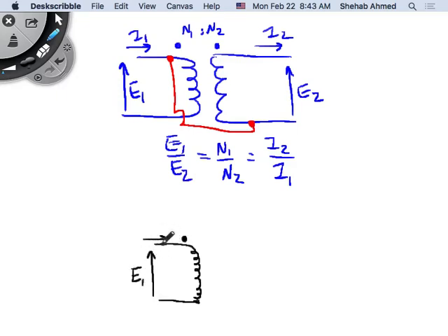The current coming in is still I1, right? But now I took this terminal and put it at the top here. So I connected something here, and put the winding of the transformer with the dot on this side still, right? If you take this and put it on top, the dot will still be on top, so current is still coming out of the dot.